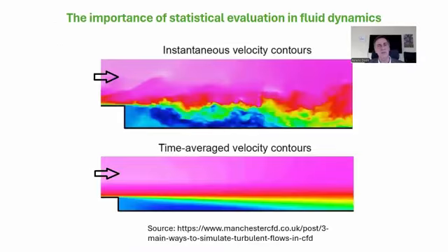Why is the statistical approach important? It is just a similarity to how fluid is mixing with high velocity and non-moving fluid. The mixture is quite complex. Turbulences here are like around the trees. But when we take the time average, this complicated feature becomes very smooth. So it is just a similarity indicating that in this complex situation, statistical evaluation gives us the possibility to get good results.